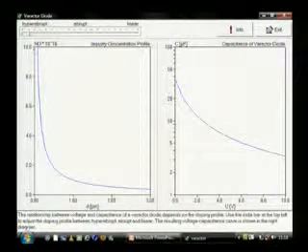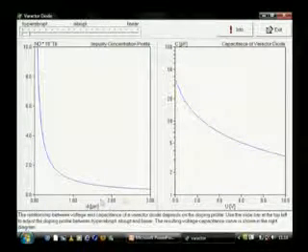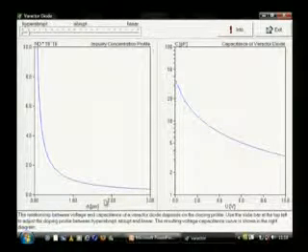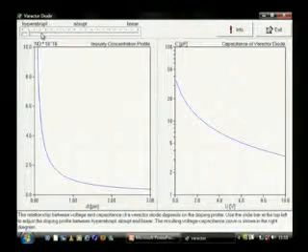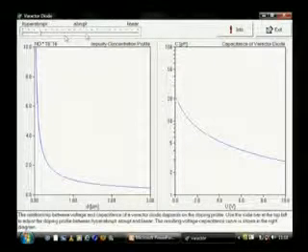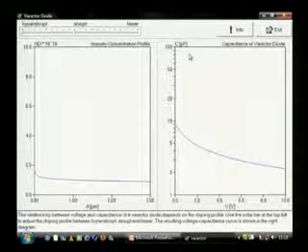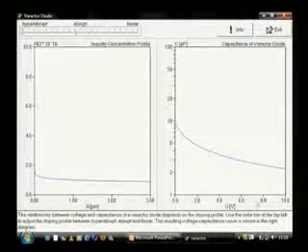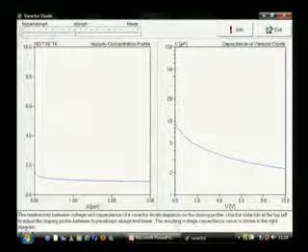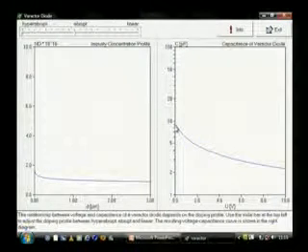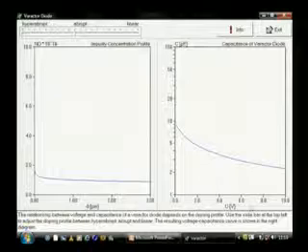One can see here that the first graph is the doping versus the depth, or say the width, of the varactor diode, and this slide bar can change the doping concentration from hyperabrupt to abrupt to linear. Initially we will put it on the abrupt side. In the second graph we have the capacitance versus voltage graph, with capacitance in picofarad on a logarithmic scale. The resulting voltage capacitance curve shows that from say 9 picofarad it is decreasing with increasing voltage.